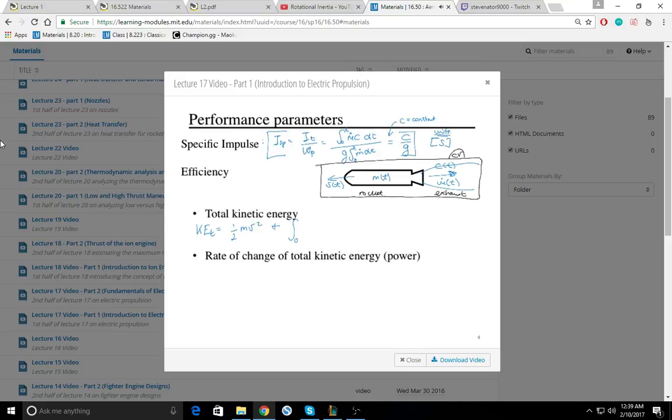So we integrate from an initial time to a final time the kinetic energy of the propellant being expelled, which is 1/2 of m dot, which could be a function of time, times the velocity, the absolute velocity of the rocket minus the relative velocity of the exhaust, squared and integrated in time. Any questions? Feel free to stop me if the pace is not right. So the total kinetic energy, if we differentiate with respect to time, gives us the total kinetic power.